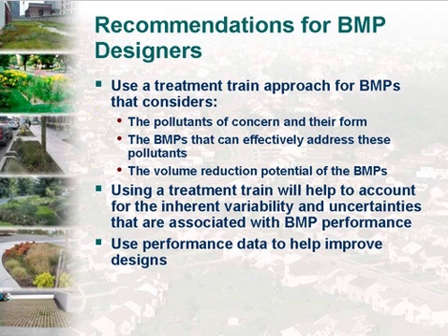Here we have some recommendations for designers. These are rather generalized, but just some things to think about. John, maybe you can start this one out. Yes, thank you. Certainly there's a strong consensus on the part of professional societies, governmental agencies at the federal, state, and local level, and design practitioners that a multi-layered treatment train approach to BMP design should be utilized. That would include both a broad mixture of non-structural BMPs and structural BMPs.